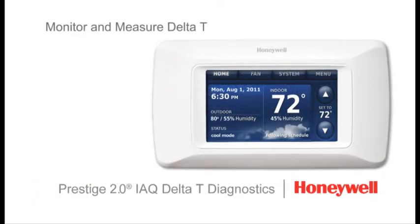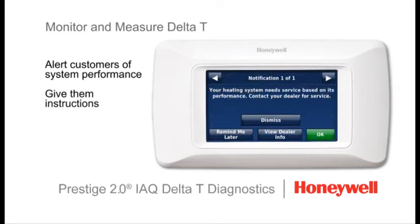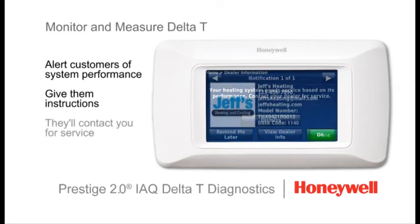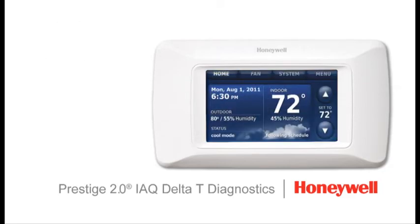By monitoring and measuring delta T, you can alert customers when their system is not operating as expected and provide them with instructions to contact you for assistance. Before getting started, keep in mind that delta T diagnostics are only available on Prestige IAQ 2.0 systems.